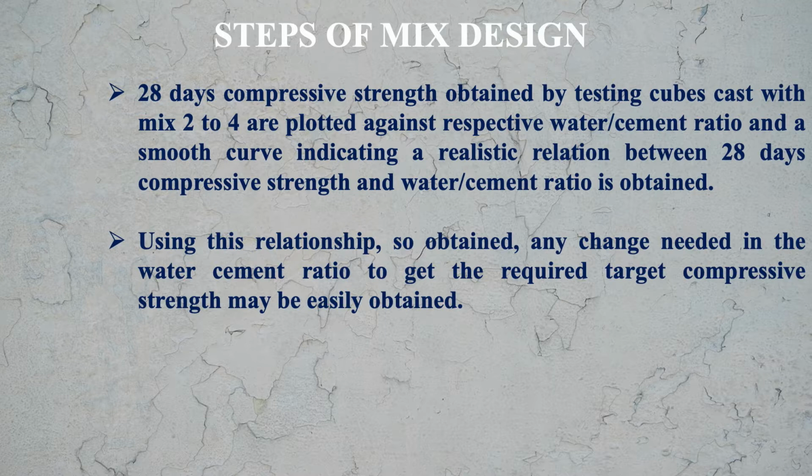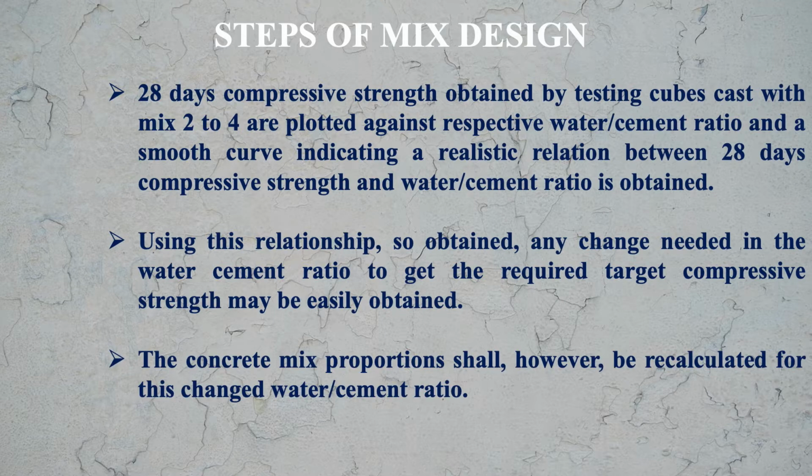So using this relationship so obtained, any change needed in water cement ratio to get the required target compressive strength may be easily obtained. The concrete mix proportions shall however be recalculated for this changed water cement ratio. Means each time if there is any change in the water cement ratio, then we have to recalculate the concrete mix proportions again and again whenever there is a change in the water cement ratio.